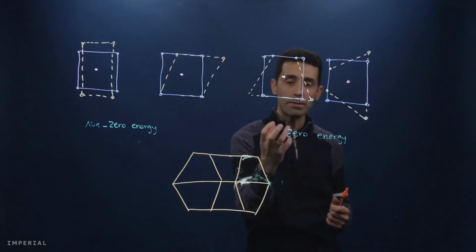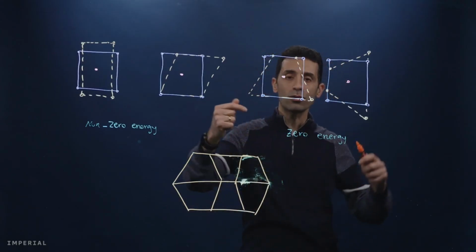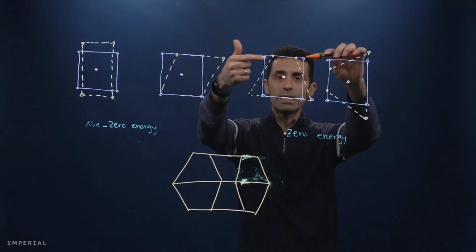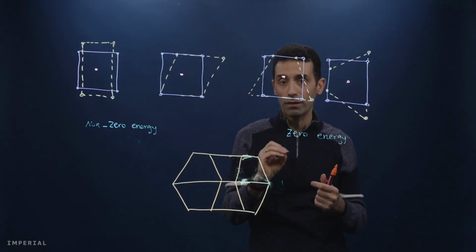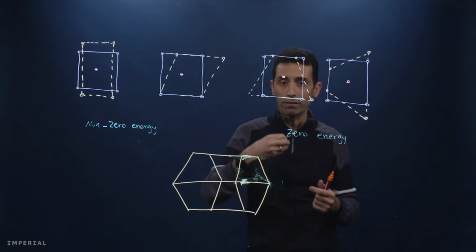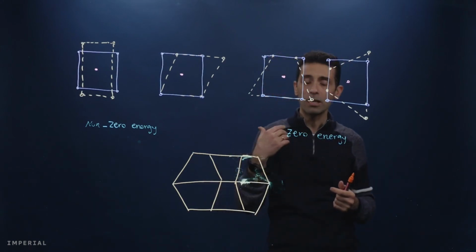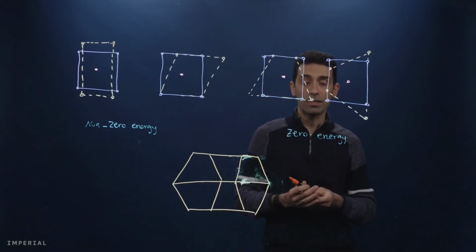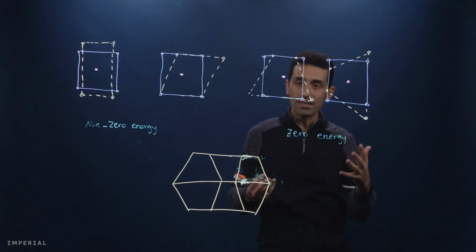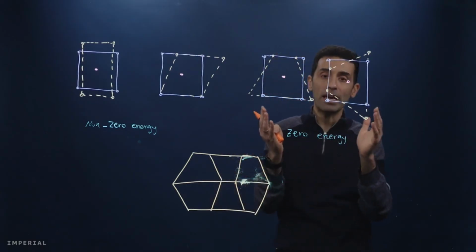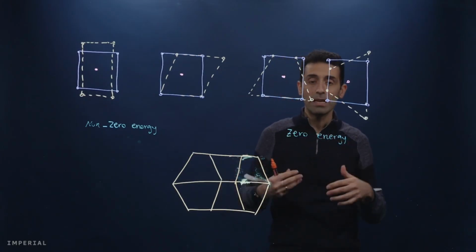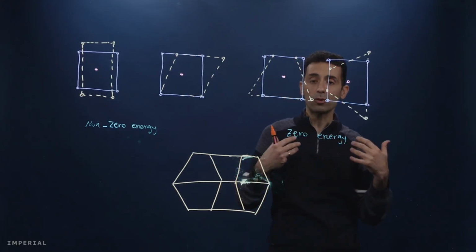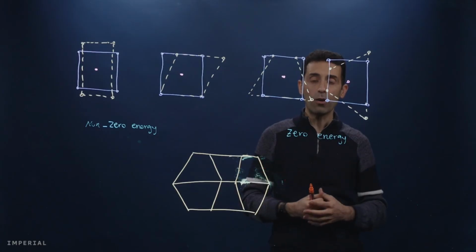In order to remedy this, the approach is to apply forces in these nodes in order to resist against this zero energy deformation. But you can imagine the forces that we are introducing are numerical forces, so these are not physical forces. As a result, there will be some energy produced within our simulation that is caused just by our numerical manipulation of the model.